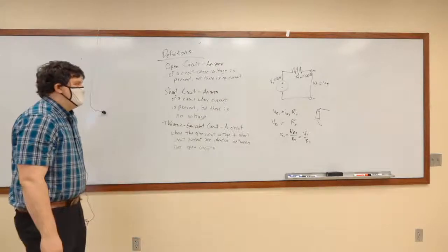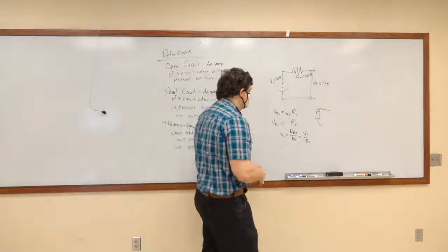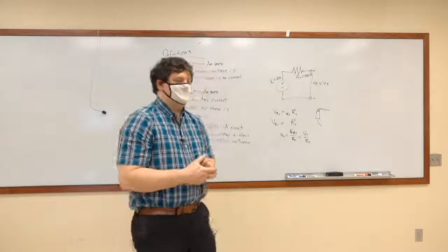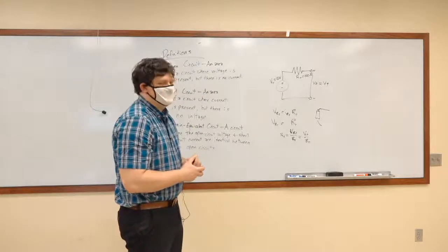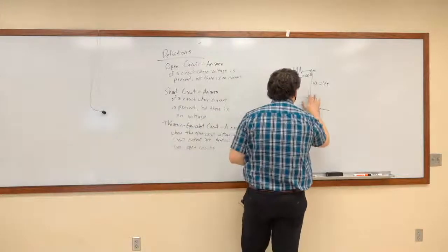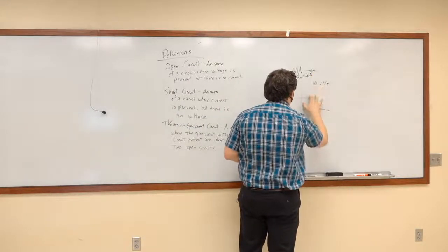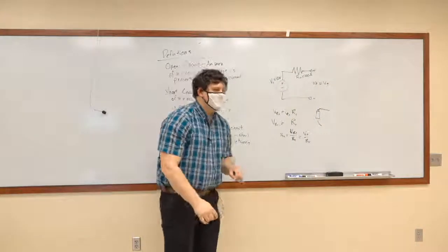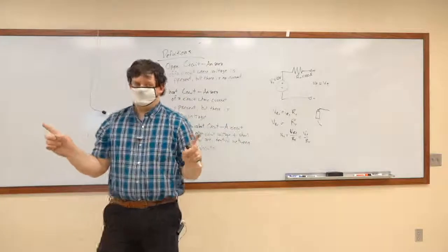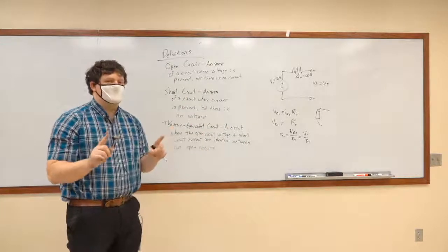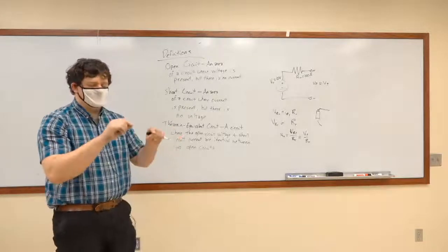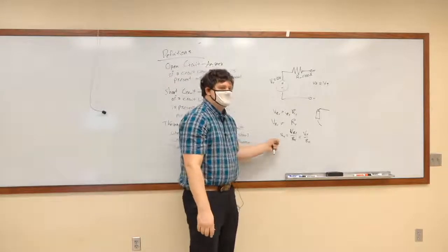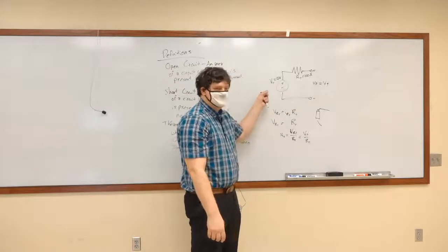The reason why Thevenin made this be his equivalent circuit is because these relationships are very simple. It's an easy pass. Okay? If we know what the voltage is between any two terminals in any circuit, and we know how much current passes through if we were to short those two terminals, we then know what IRT is, and we know what VT is.